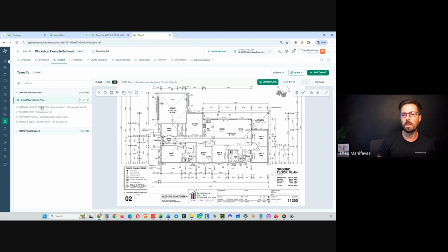And then the other scenario is that originally I had, say, plaster, just calculating, and on face value, it does make sense. Like you're measuring the ground floor area, reflected ceiling plan, it's just plaster square meters on the ceiling as well. But then, depending on the house, and most houses these days, I'd say that you're putting WR board in your wet areas. So then what you're forced to do is go in and do a deduction for that wet area plaster. And shout out to Rob Rule if he's on the call.